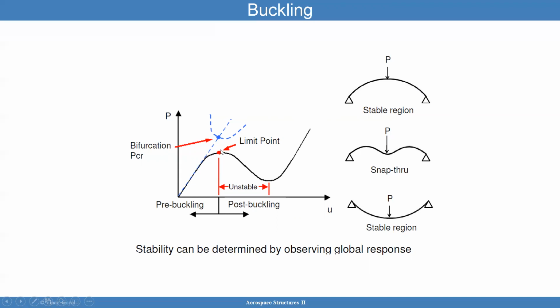But there's a point at which you will get some amount of deformation. Now that's nonlinear. And at that point, you're going to start seeing something we call snap through, where if I did this under load control, so I'm applying load and increasing it, to say 50,000 pounds is the limit load. If I increase the load any further, it's going to jump to the next curve here. And that means you have had a significant amount of deflection jump from this point to this point. So it went from this point to the bottom.